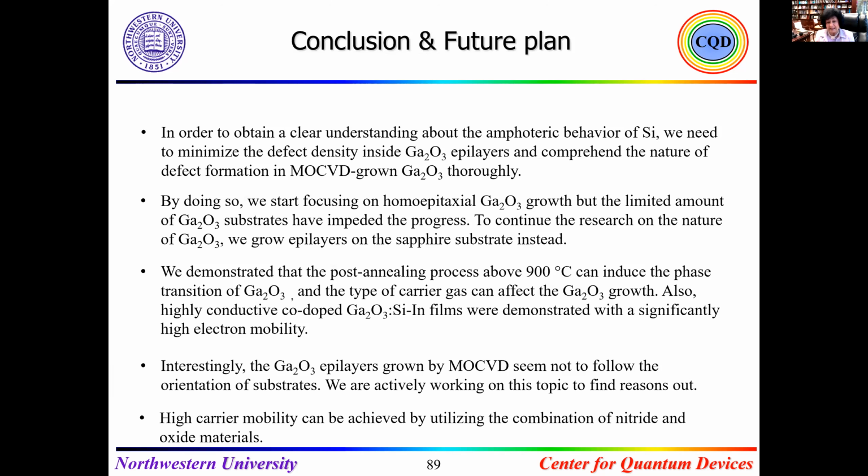So I would say that with all of this result, the p-type, the high temperature transistor that we did, corresponds with all of the findings that we found. It means that if we grow under nitrogen carrier gas at very high temperature, and dope with silicon, with the silane at the 6:3 ratio, we can have p-type, but unfortunately, as we can see, it is defect related. So the study at the present time is how to eliminate the other defects in the epi layer, in order to understand much better. So the work is continuing.